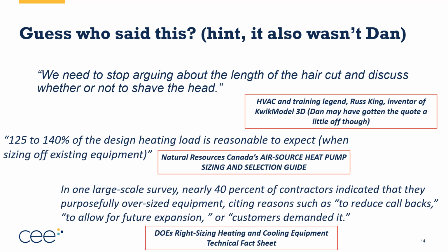We can address each of these, and we're going to try to throughout the rest of this session by talking about making sure we get quality data entry, making the differentiation of what's worth worrying about, that R13 versus R15 in the wall, or the R13 versus R0 in the wall. And then we're going to look at the different types of load calculations and whether or not we think they've got this flexibility to go over 140% or more, because there's a bunch of different ways to do load calculations, and we want to make sure that we're doing, again, the things that are somewhat reliable, repeatable, and produce reasonable results.